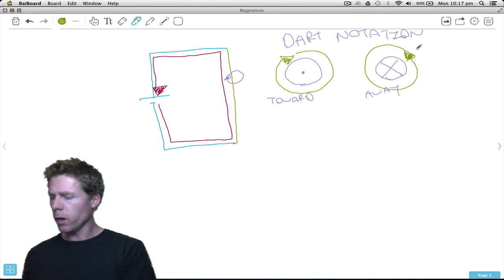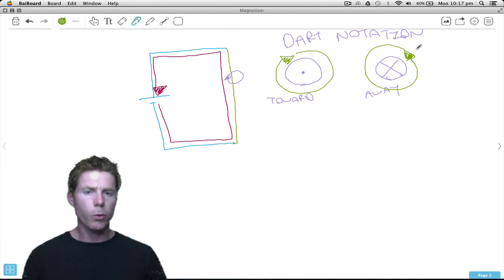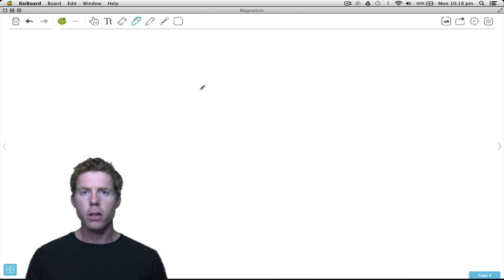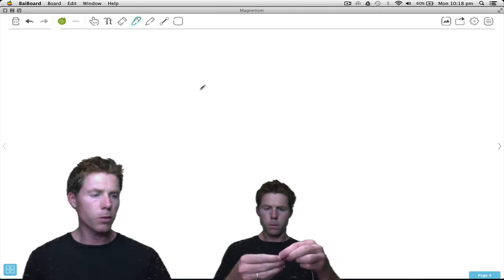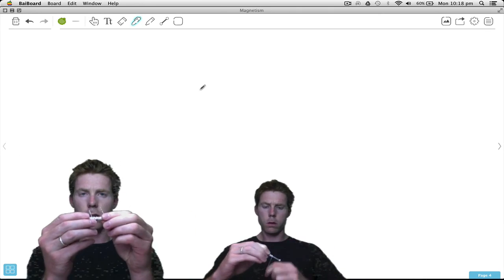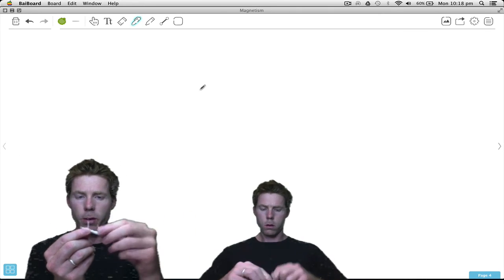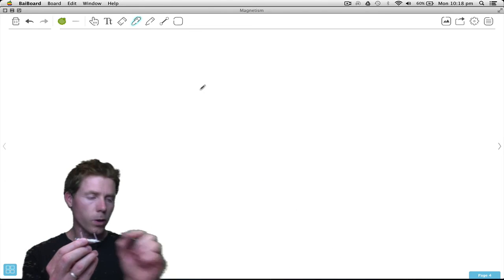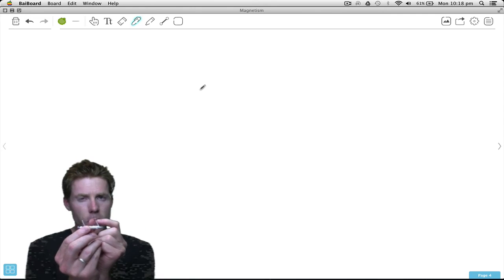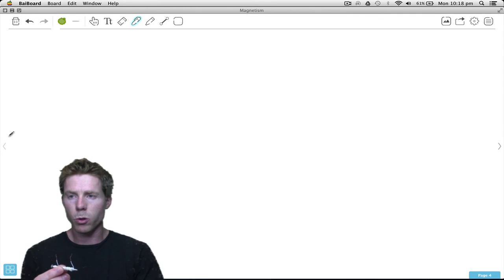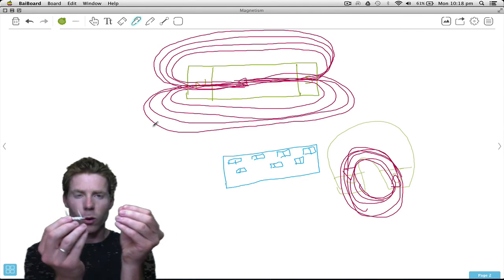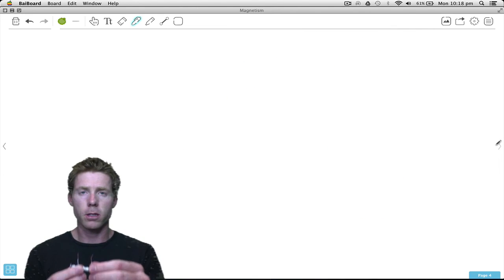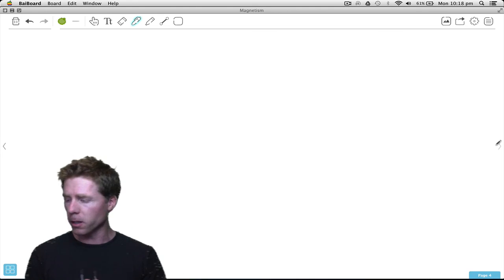Alright, so why did I just tell you about that then? Well, we can actually enhance the effect of this. So what I've done here is I've got that same piece of wire, just like this one, and I've got a screw, and I've wrapped it around. When I do that, I actually combine all of these little magnetic fields, put them in a tight space, just like when we were talking about this before. So if we can get all of those in a tight space, we can enhance the effectiveness of that magnetic field and make it a stronger magnet.